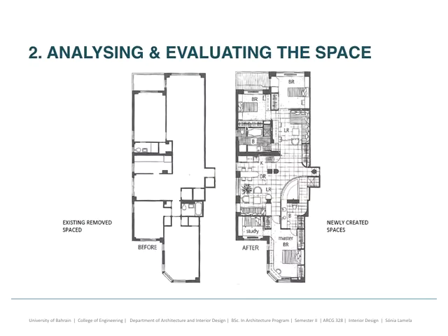When we are doing this type of analysis and evaluating the space, this could now be focusing on the interior design stage and on pre-existing buildings, like in a refurbishment stage. One of the things that you should look at is the existing spaces and the things that could be removed without affecting the structure, or in this case pipes coming from bathrooms or kitchens. So let's say the fixed elements that you cannot get rid of, or that you shouldn't even move, and then the ones that are flexible enough to provide a different type of layout.